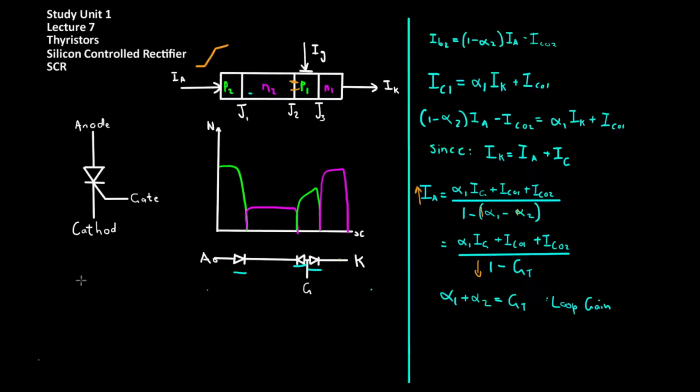There are of course other types of SCR, such as the asymmetrical silicon controlled rectifier. The primary characteristic of the ASCR is that it does not have any usable or repetitive reverse blocking ability, hence the name asymmetrical. By sacrificing this reverse blocking, there are significant improvements: a lower on-state voltage, a higher forward blocking voltage, and a faster turn-off characteristic than the classic silicon controlled rectifier.